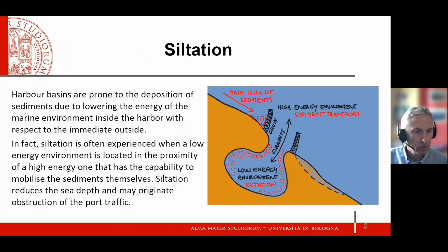And therefore, if we protect with groins the band close to the coastline where longshore sediment transport is significant, then we reduce the flux of sediments at the harbor entrance.